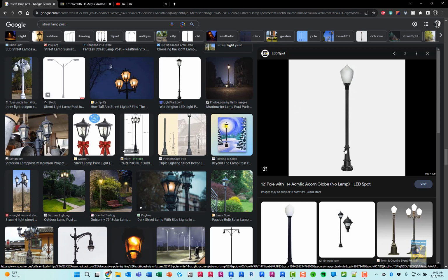With a family like this, you can just start with a single light fixture family and build the housing and either save that as an individual family and then build this housing, this vertical structure, as another family, and then nest this light source family into the host family that is the structure. And the reason you may want to do that is because you might want to create different housing designs and then use a family types parameter to swap out in the host family.